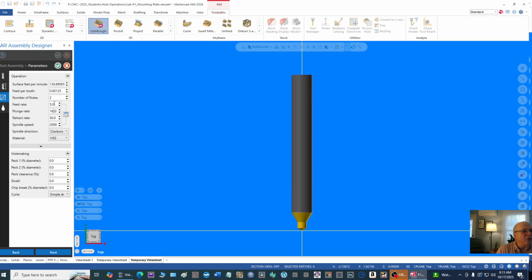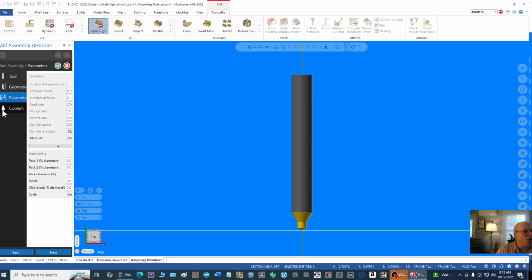And then my feed rate now is the most important thing, and I'm going to put in here 20 inches a minute, so 20 point. This down here is not going to be of any value to you right now, so I think we pretty much covered everything. This right here is coolant, but we'll be dealing with the coolant situation after we get started programming the machining operations.